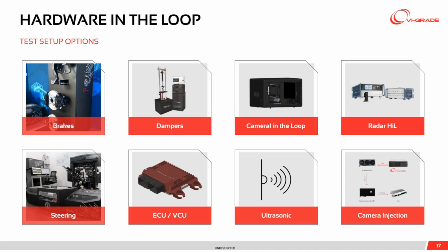As we move into ECUs, we can also simulate in real time a lot of the vehicle protocols, such as CAN bus, automotive Ethernet, and such like. So we can feed data to an ECU in order for it to make its decision and provide input back to the simulation. So we've actually got examples of developing ECU algorithms within the context of plugging it into a virtual simulator. Camera in the loop.